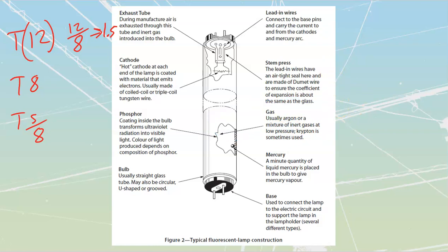And then we are also going to have mercury. What do we know about mercury? Well, we know that mercury is a dangerous, dangerous substance. So be careful with these bulbs. Do not just smash them into a dumpster. If you do break one and you get the inside coating all over yourself, even if you don't visibly see it, make sure you wash up before you eat, because it's really harmful to be ingesting any mercury. It is a small amount that is inside of these, but it is still a dangerous amount if you get exposed to enough. That mercury requires these to be properly recycled as well. These are not dumpsterable types of components.